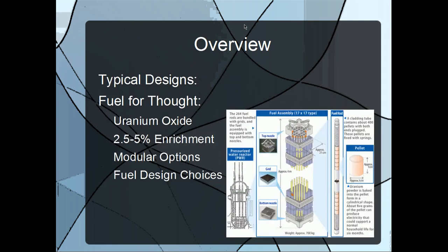The fuel organization of this module, for example, is a reduced height 17 by 17 standard light water reactor fuel assembly. Each assembly consists of 264 fuel thimbles maintaining fuel pellet material made of uranium oxide held in a Zircaloy-4 cladding and enriched to 2.5 to 5% by weight. The fuel is maintained in power modules that can be connected according to maximum power requirements. The current full-scale design maintains 12 modules connected together, with each providing 45 megawatts of electrical power for a total capacity of 540 megawatts per plant.